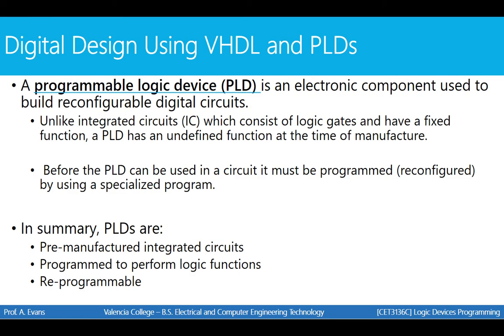So a PLD stands for a programmable logic device. It's an electronic component used to build reconfigurable digital circuits. So if you think about your typical circuits from Digital 1 and Digital 2, you use different ICs, which are integrated circuits that consisted of logic gates and had a fixed function. For example, an AND gate can only do one thing: follow the truth table for the logic idea of AND.